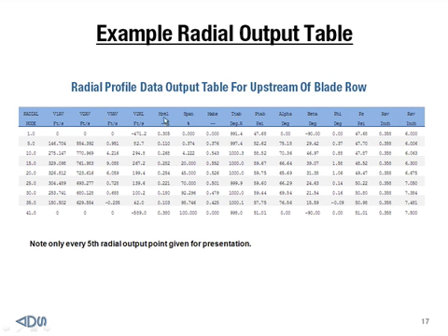Next would be the relative Mach number, the percent span, the absolute Mach number, absolute temperatures, pressures, the air angle, meridional air angle in the absolute and relative frames, the pitch angle, phi, the static pressure, the axial location, x, physical location, and the radial location.